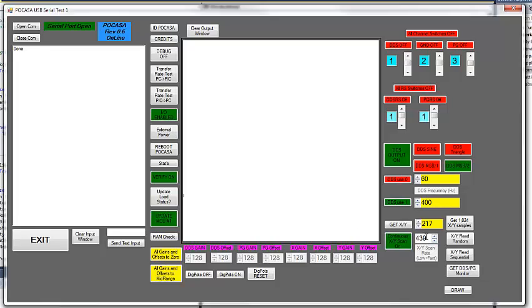If that's 1,000, this is a number of milliseconds between scans. So if it's 1,000, it's once every second. If it's 500, it's twice a second. 330 would be 3 times a second, and so on and so forth. I get down here to 1. It'd be pretty close to 1,000 times a second, although it's not quite that fast. Because if it was, it would be filling up 2 of these lines every second. So I got to tighten up the code just to make that a little bit quicker.